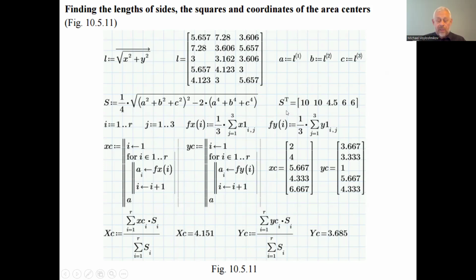This is the description, equality sign. This is assignment, shift columns, two buttons. If we do not transpose the columns into rows, we will have the vertical location of this vector, which is possible, but more comfortable to locate on the page of Mathcad is the horizontal location.